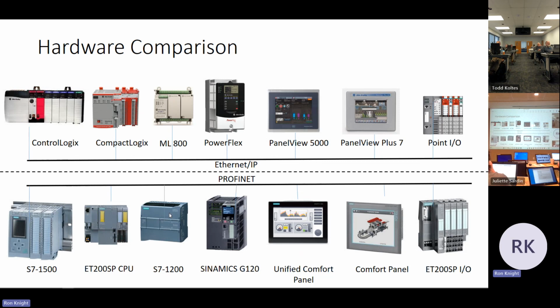Yeah, you've got onboard IO. Yeah, you can do expansion IO, but then you can also do up to 16 remote IO racks, and you can also do safety there. And there are some bells and whistles that you have in here that you don't have here, and it programs with the same software as the 1500, so you don't have to learn a separate software package.